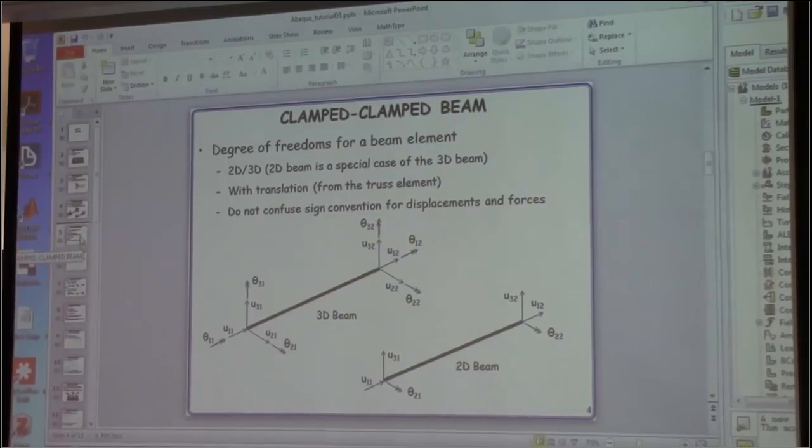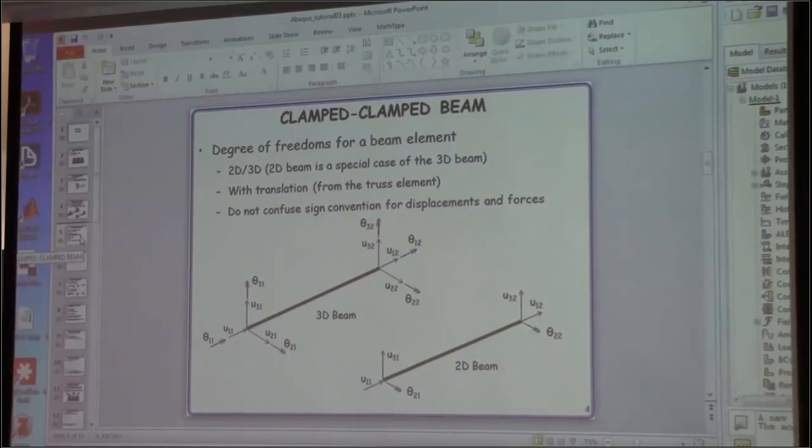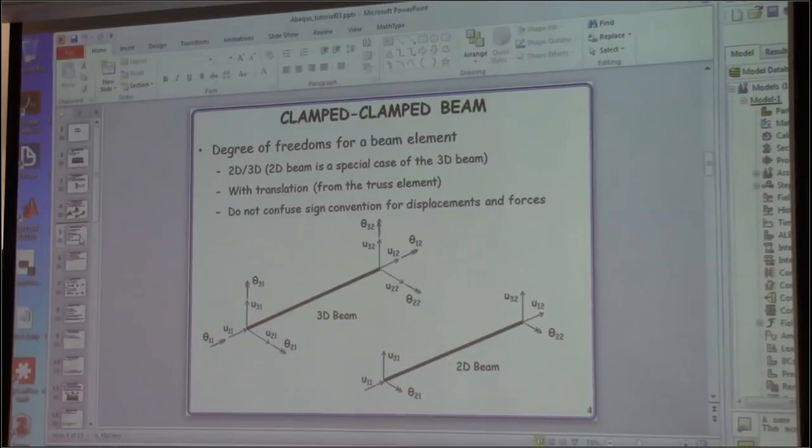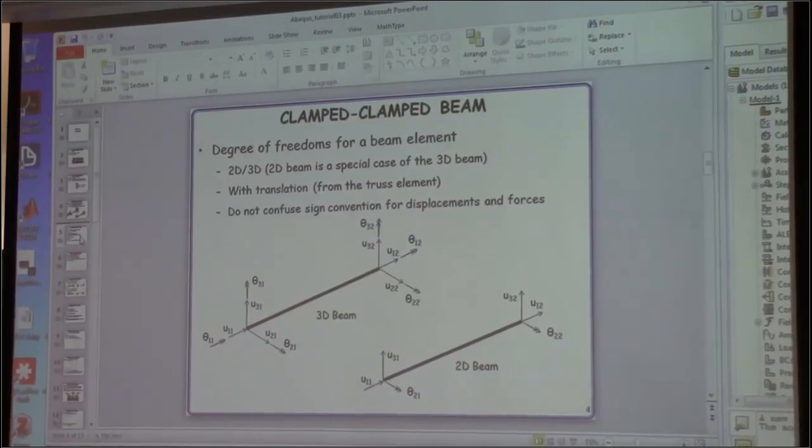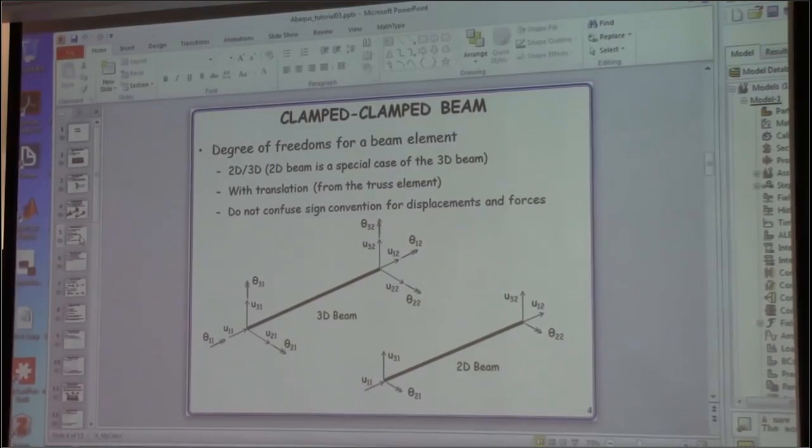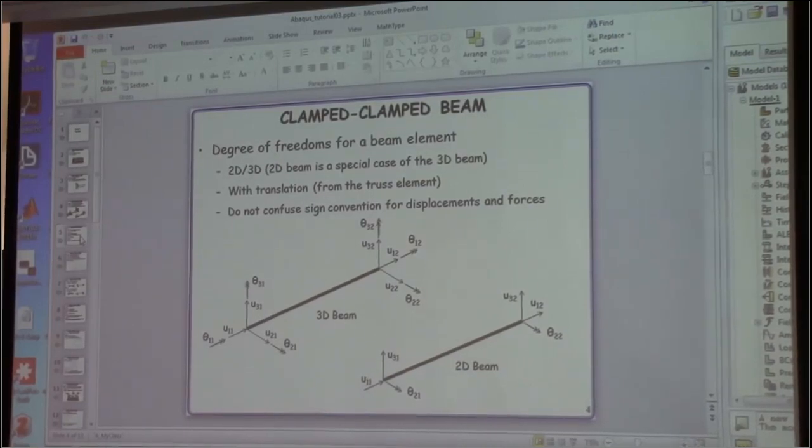And also in the truss problem, because we only have the axial force, the results we probably need to know are the elongation and sigma xx, right? But for the beam problem, once we have bending, we have the bending moment result and the deflection, the displacement in the y direction, and the sigma xx is also different.